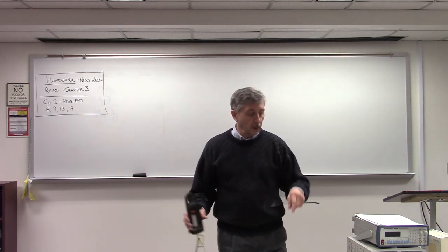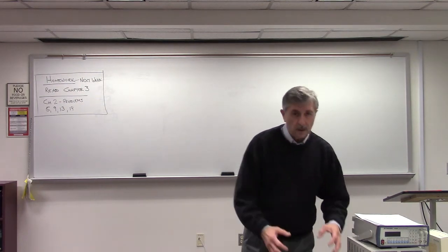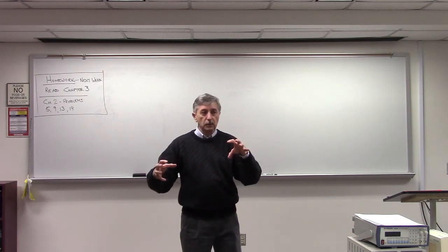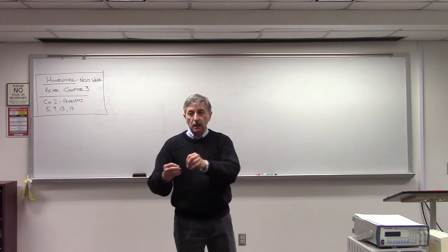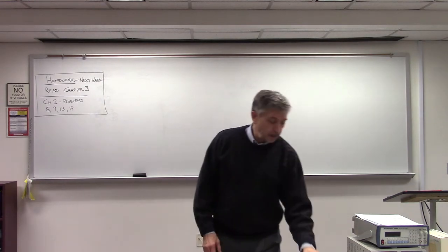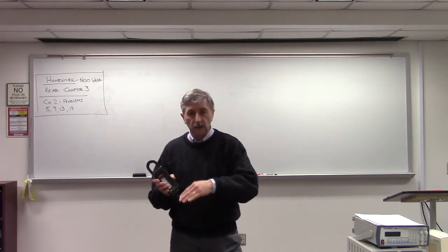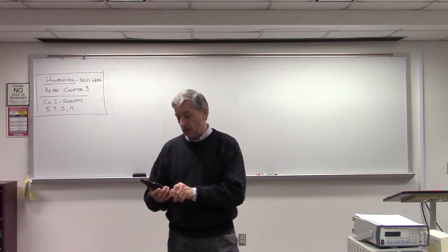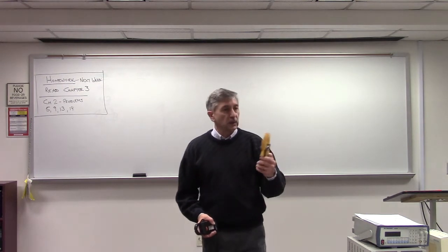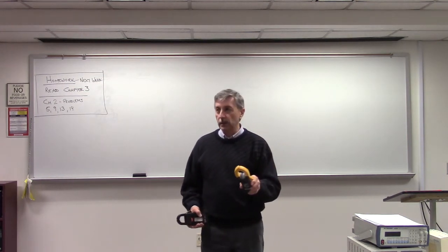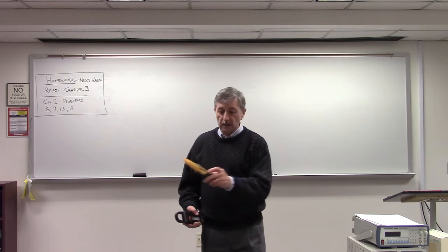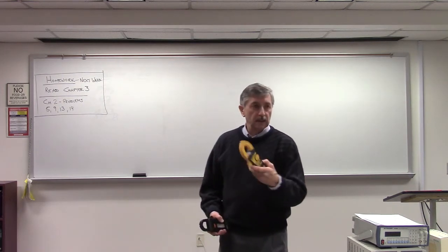They call that full load current. And the inrush is caused by the fact that the magnetic fields in that motor are just expanding very rapidly. The motor won't turn unless those fields are present, and that buildup of the magnetic field causes an inrush. And I can see that here with that needle. It'll jump and then come back down to whatever value it settles in at. I can't see anything on this. It's too quick. This meter's not fast enough to record that jump. It's only a fraction of a second. So even though this has a max-min feature, even then it doesn't catch it.